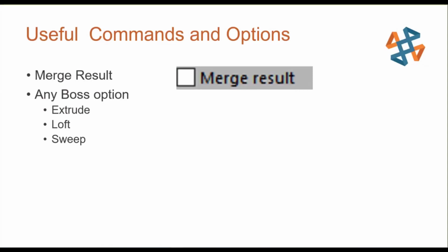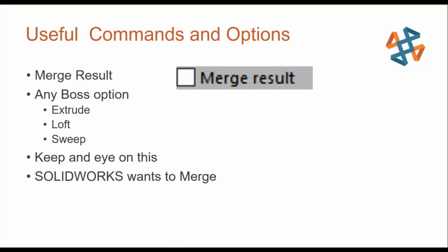If it's merged, SOLIDWORKS will join the bodies together, or the feature to the existing body. If you unselect that, it becomes a multi-body part. Now, a couple things with this checkbox. I always say keep an eye on this, because SOLIDWORKS always wants to merge the bodies.